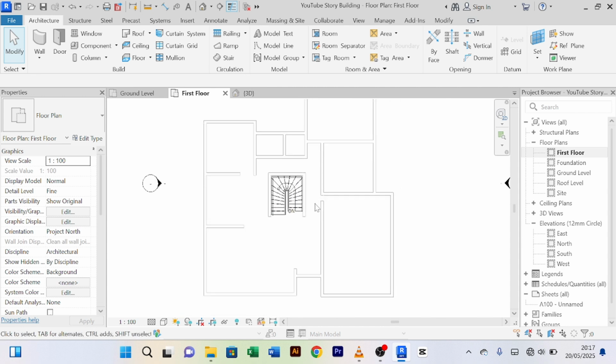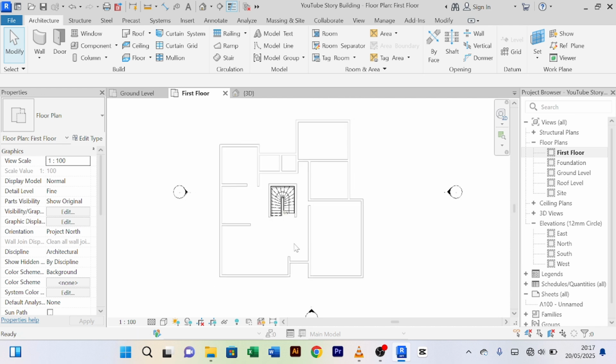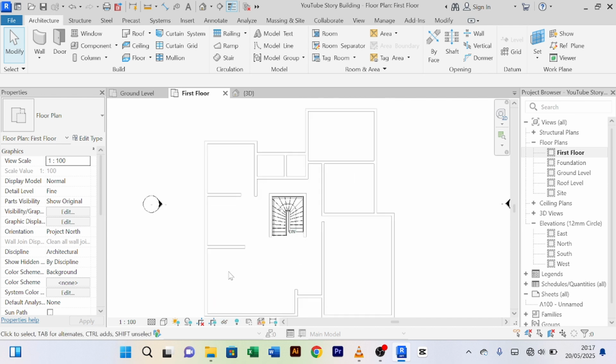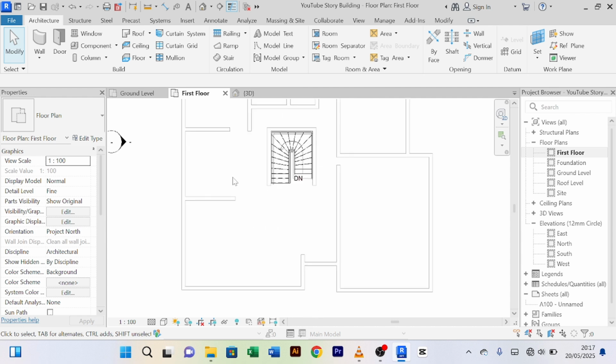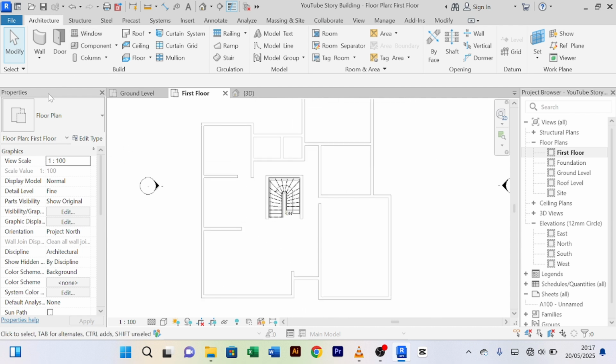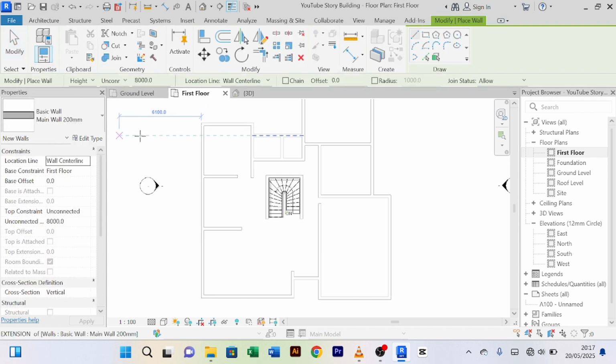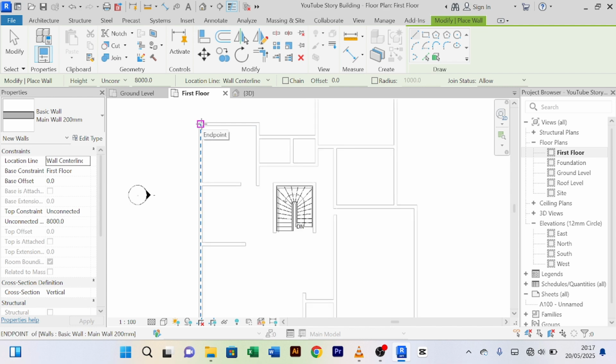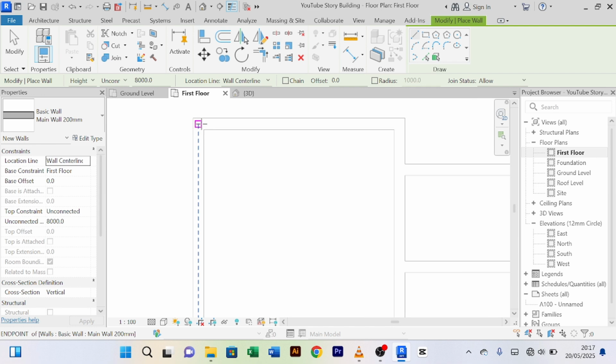So now we're going to create our walls here. I'll just create something simple following these walls. I will not do a lot of measurements here. So we come to our wall, we select wall architecture, and it has selected the wall we created for the ground floor. We could even just sketch by picking lines, but I want to draw. So I'll just draw. I make sure these dotted lines are in the middle of this wall so that the wall we are drawing doesn't go offline.